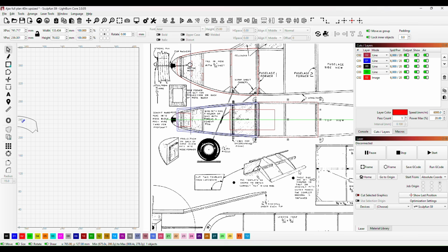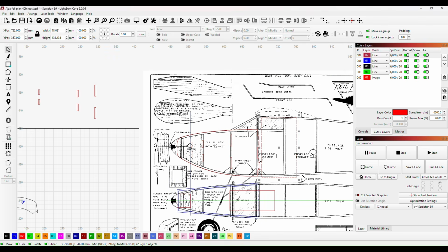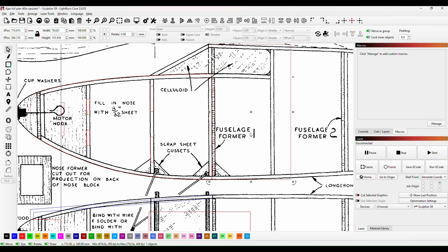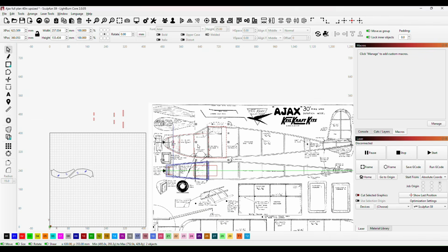So if I press full stop again, that'll turn back round, and I'll bring this back up and put it back in place here. I'll do that by grabbing this line and bringing it over till it snaps onto the other red line, and then using Control and Shift and the arrow keys, I just bring it up into place, and that looks absolutely spot on to me. So with that selected, if I press Control and then select the side panel as well, I can bring them both over just like that.